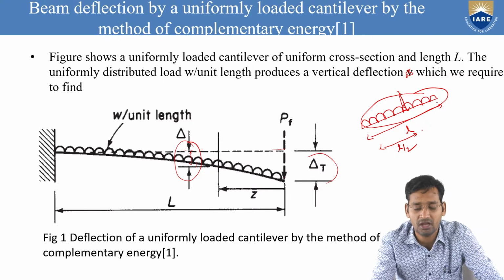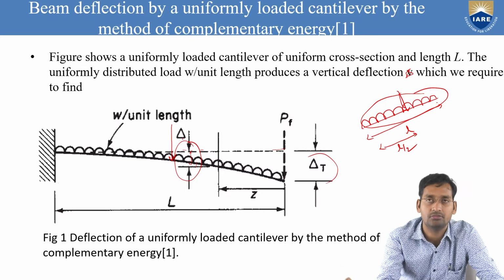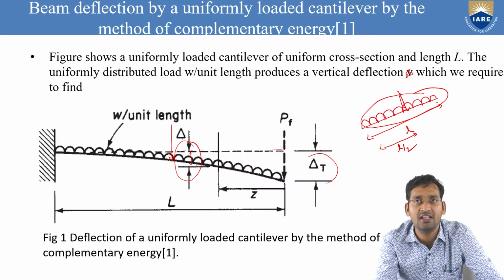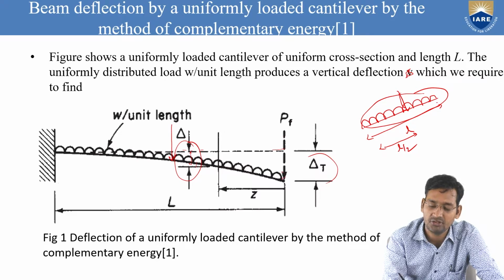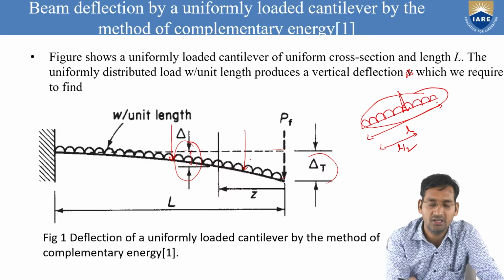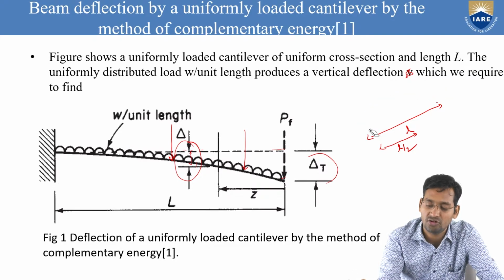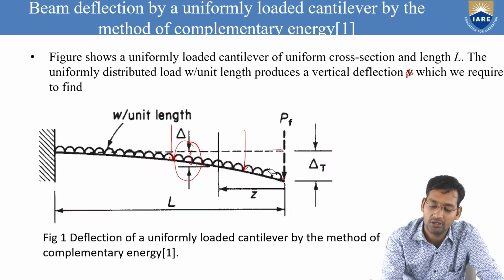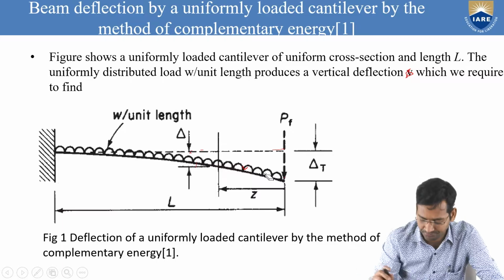So in this case we cannot take the fictitious force at L by 2; we can take it anywhere else. It's not necessary to take it at the end point only, from there you just have to take the distance, that is simple.